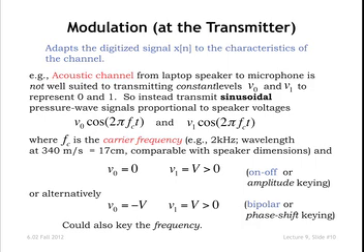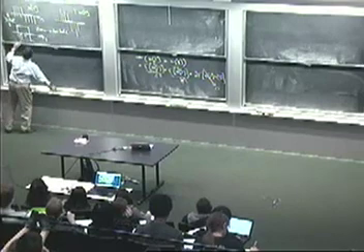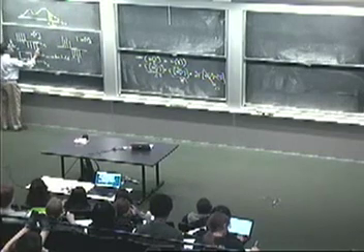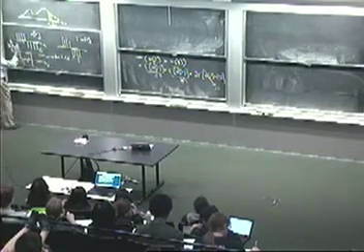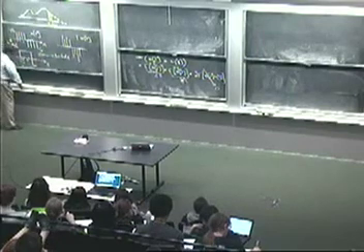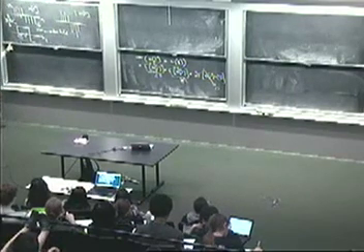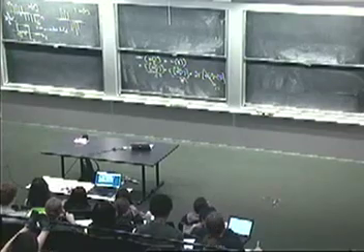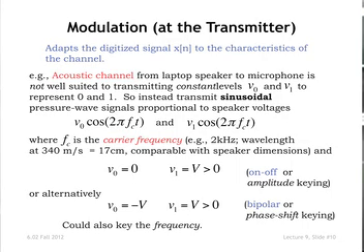You would like to transmit these two levels, V0 and V1, to represent the 0 and the 1. I'm just generalizing here. I'm just saying that there's some level V0 that represents the 0, and there's some level V1, and that will allow you to pick different possibilities here. So what's typically done is, instead of trying to transmit the DC, you transmit a burst of a sinusoid, because loudspeakers like sinusoids, provided they're at the right frequency.